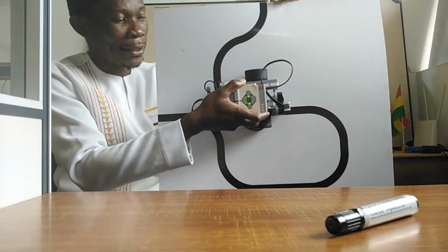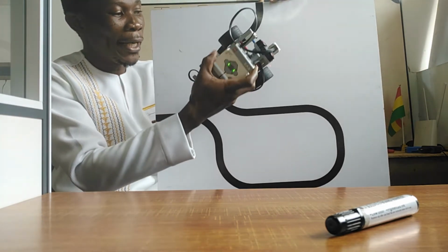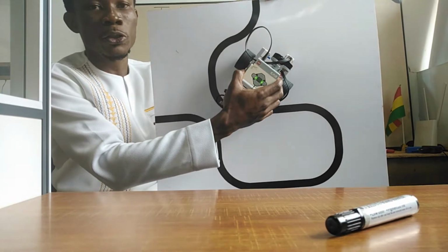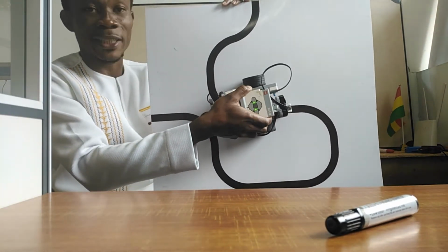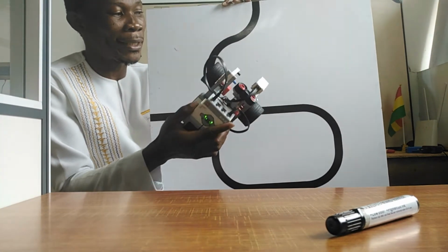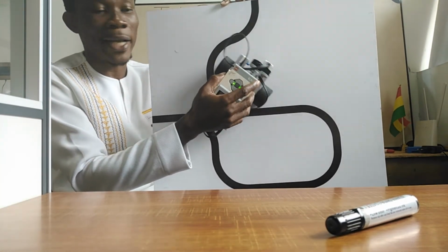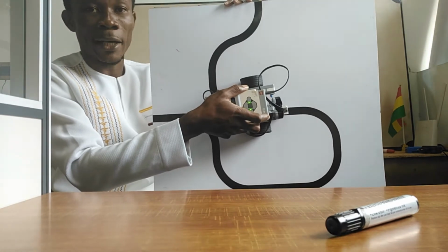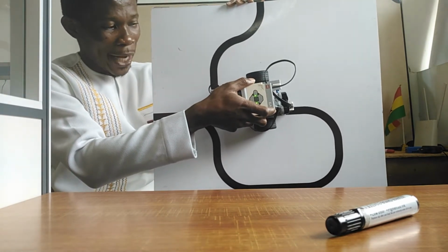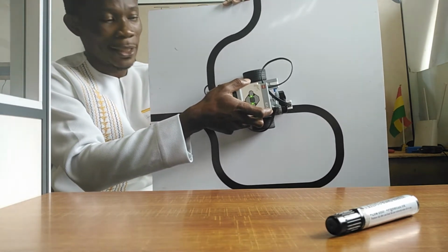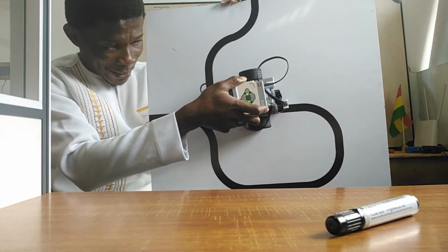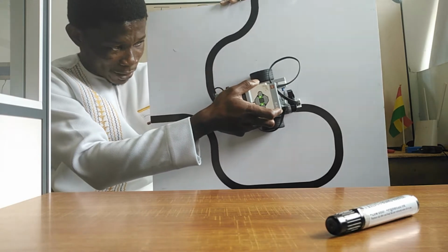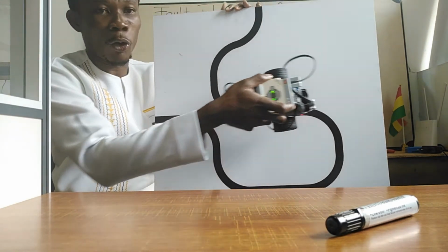Now, if this light sensor is calibrated, then it means on the white surface it is going to have 100% reflection, and on the black surface it's going to have 0% reflection, because we are calibrating the light sensor to have perfect reflection on the white and perfect absorption on the black. So at the middle position, we are expecting 50% reflection, that is half on white, half on black. Our system is supposed to maintain this position, that is the light sensor at that position, while we navigate the black line on the white tile.